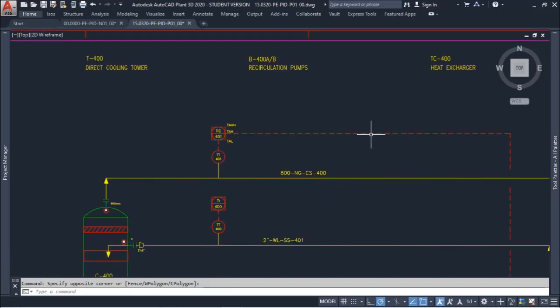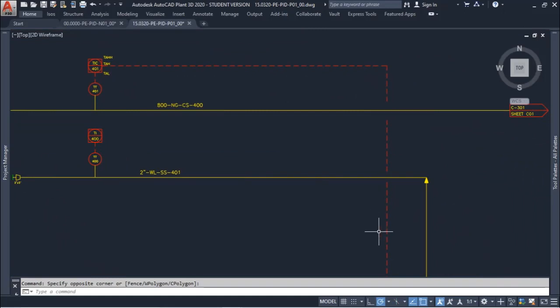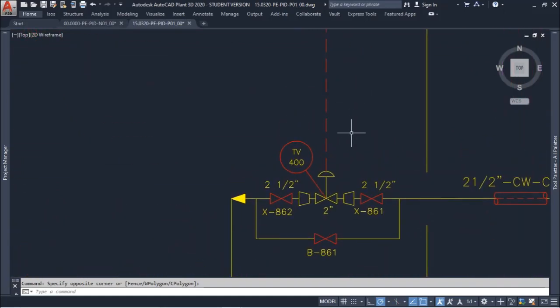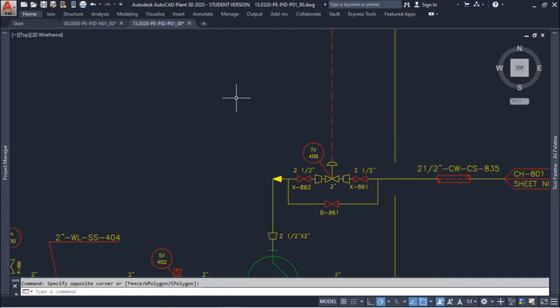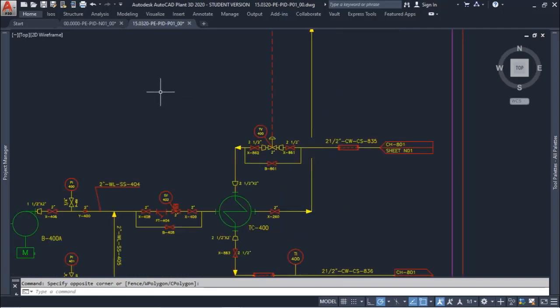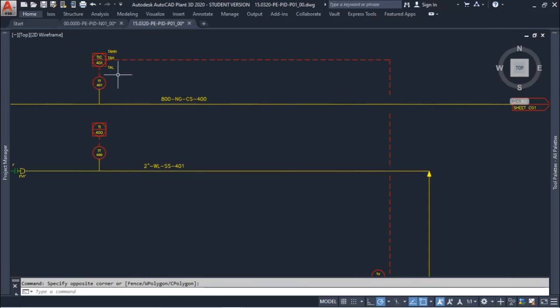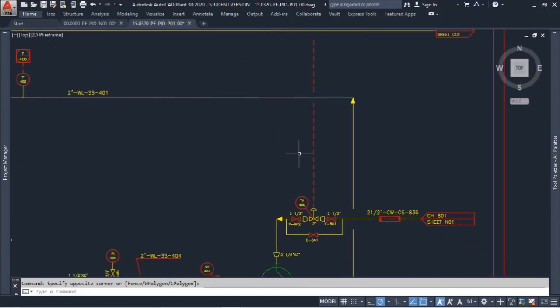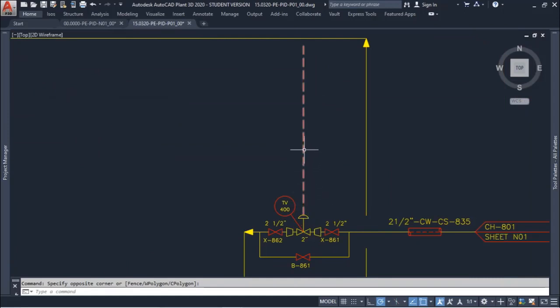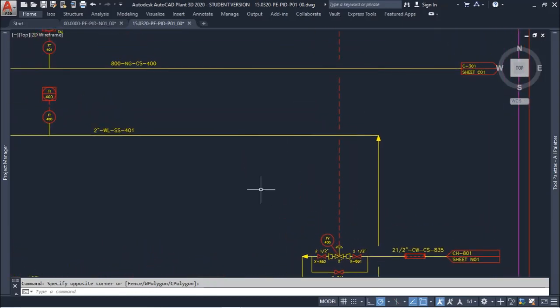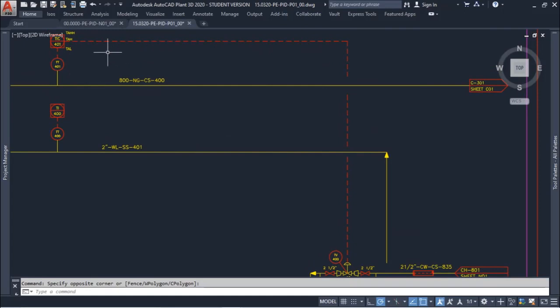And TIC sends the signal to the control valve, and the control valve will modulate based on the signal. You can see that in this P&ID, the representation of the control loop is very simple. We only have some boxes and an indication of alarm and shutdown, and it would be interesting to have an arrow on this dashed line, but if you get familiar with P&ID, you will know that the signal goes from the TIC to the control valve and not the opposite.